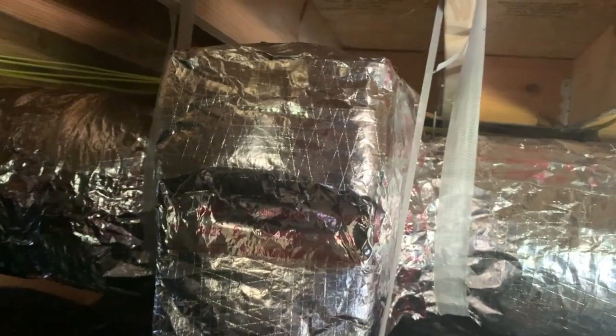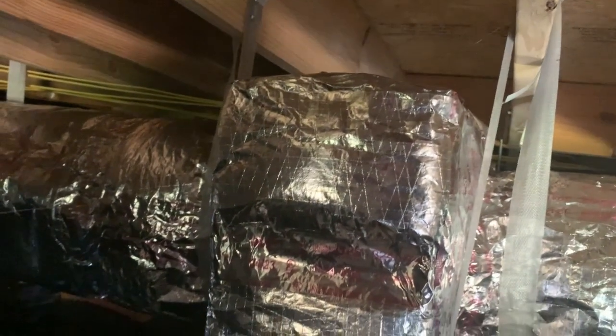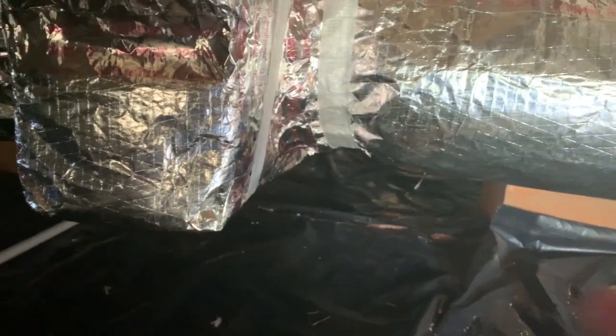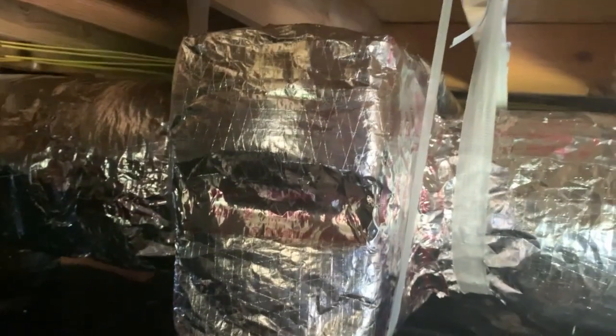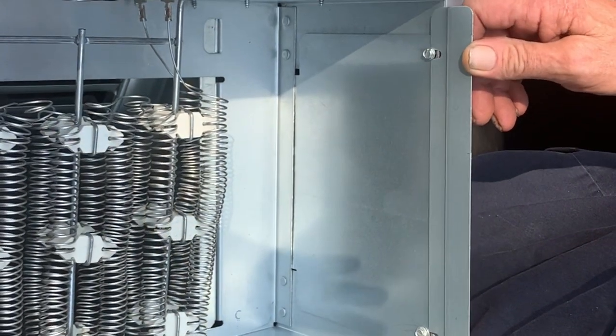Okay. Used all thread and bent at a 90 on one end, drilled through the wood, stuck it in there and bolted it down. Normally Dad usually uses unistrut to hang a unit, but they didn't have any, except something way too big, so we just used some of this slotted angle iron. It worked fine too. So then we set the indoor unit, and we put the flanges on to mount these boxes, because the unit is actually right there, as you can see. These boxes screw on each side for the return and the output. Bend in the crease and then slide in there like a flange.